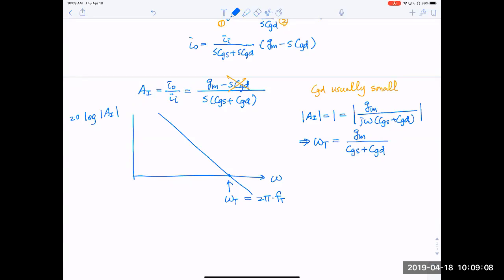But if you do have an efficient terahertz source, it can be used for imaging concealed weapons on people going through. You cannot see with visible light, but with terahertz, you see exactly where the weapons are. That's why it's of interest. As wireless communication, it's very difficult to generate and detect terahertz. So it's not going to displace wireless communication anytime soon. It's more used for niche applications where you can only see with terahertz.